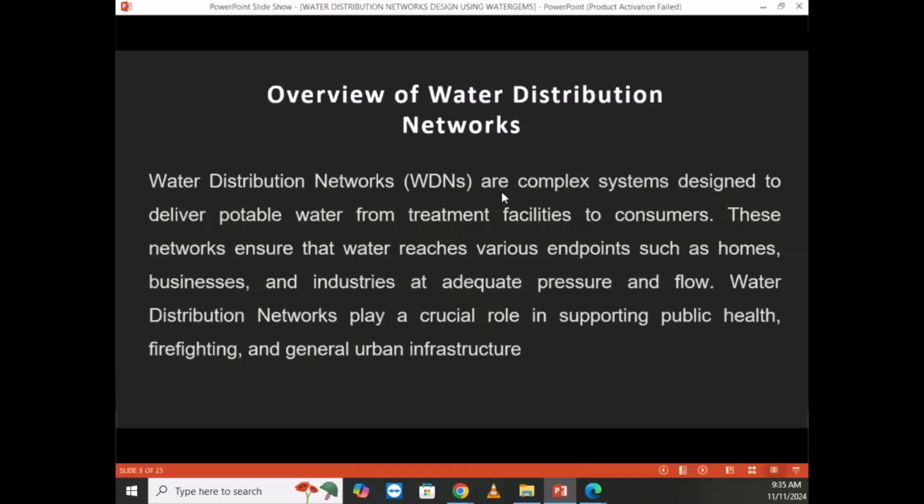From the boreholes, your water needs to be treated. It's only disinfection. Yes, that's also a treatment facility. So when we talk about a distribution network, it starts from that disinfection system and goes to the distribution network. But by saying water supply, it starts from the source, from the borehole, where you fetch water.